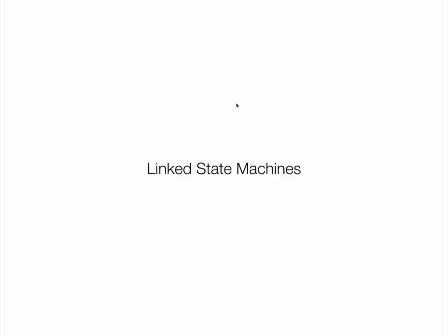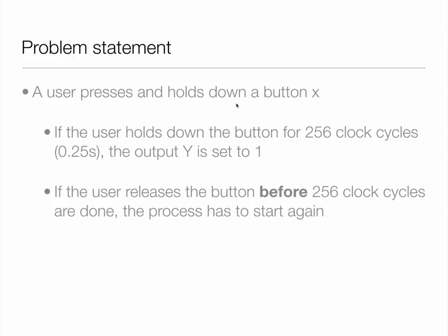All those things you can go and model and design, and then you can tune it up and hone it down and use best practice. So for counters, for example, you might use a little bit of cascading to keep the number of gates down, at the risk of adding propagation delay, but there's always a balance. You might optimize a design rather than just build a massive great state machine to do it. And that's kind of the example I'm going to use.